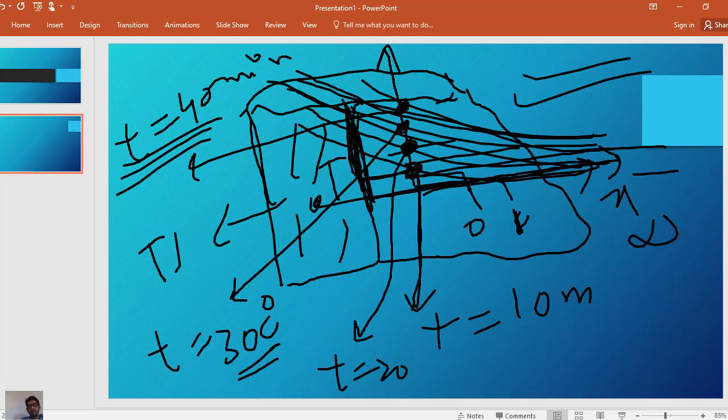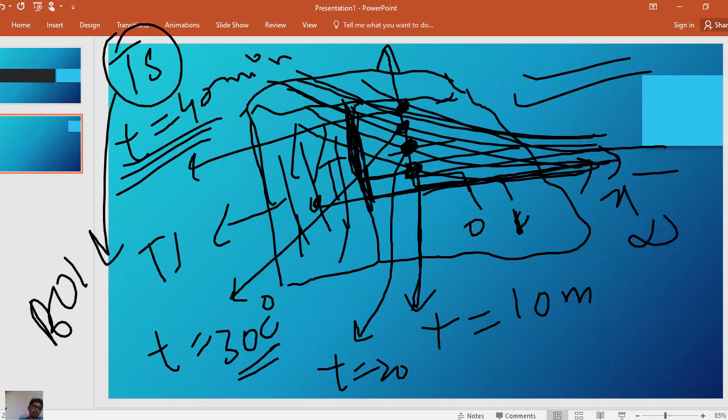So this is all about heat transfer in the semi-infinite solid body. This is all about the relation between temperature, x direction and time in the semi-infinite solid body. We will discuss other cases. This was a simple case in which the surface temperature was constant. A constant surface temperature usually occurs in boiling or condensation phenomena. So this is all about heat transfer in the semi-infinite solid object.